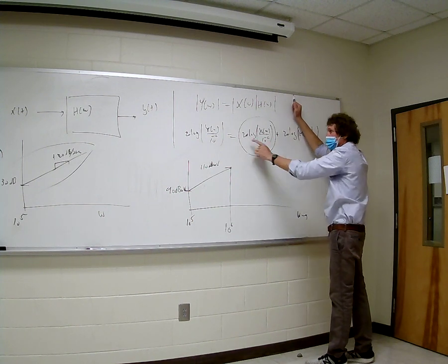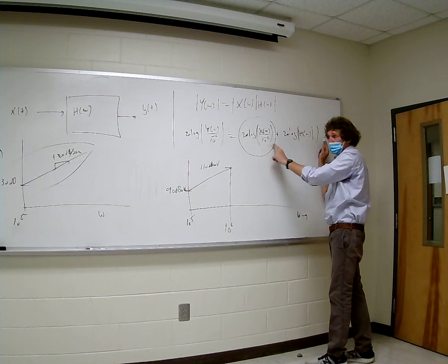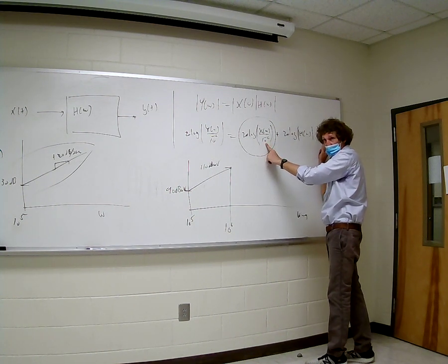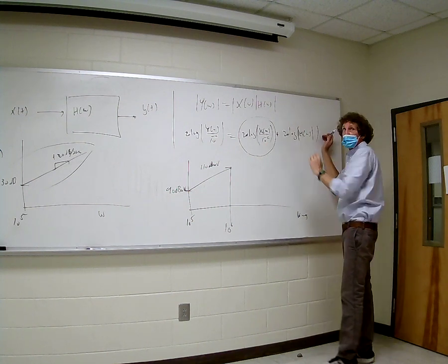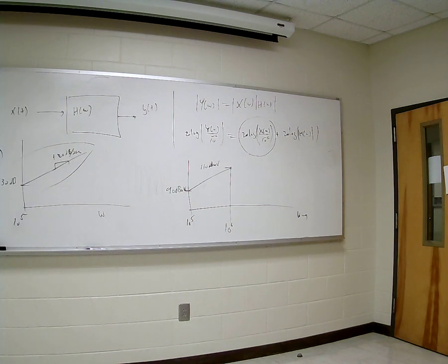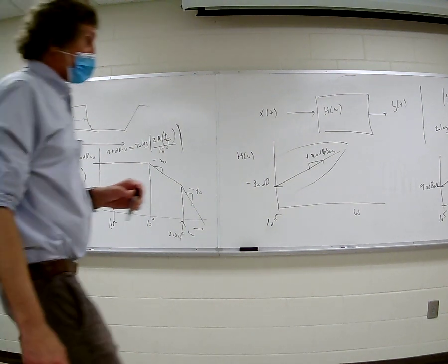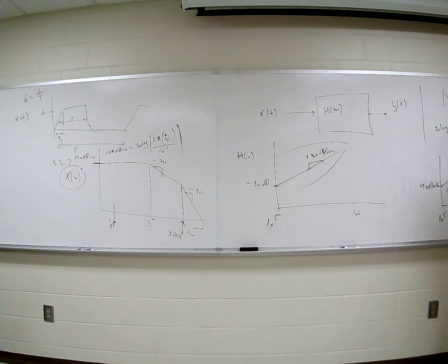Now this is the one thing I've got to tell you. You have to watch this. This will be in dB microvolts. This is dB. You all with me? The microvolt stays there in this one. This doesn't. It's still fine. You can add dB to dB microvolt. The micro just indicates the unit it was normalized to. All right? It was normalized to 10 to the minus 6. You don't even have to use a unit if you don't want to. But because we're electrical engineers, we use volts because it's common. Everybody with me? You could have just put a mu symbol there, but that's okay. Now, do you understand how I got to 10 to the 6th?